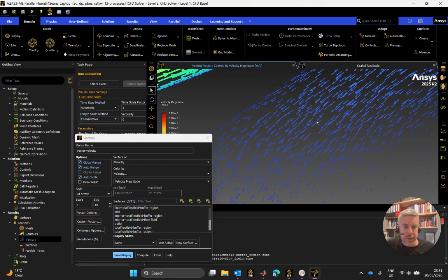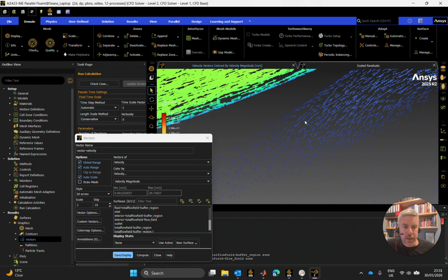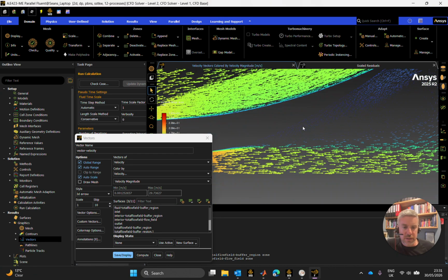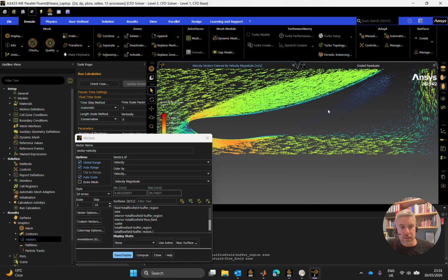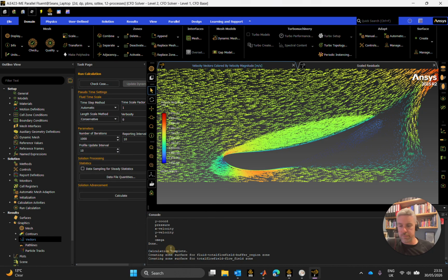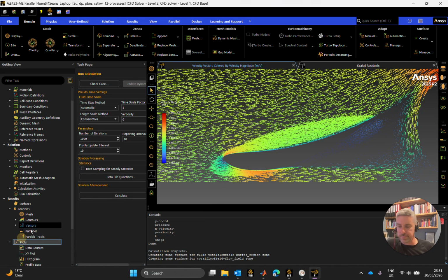This, from an aerodynamic perspective and how we design the front wing, I think this region here is probably the most telling, where we see the separation occurring, which means that we need some way to inject some high energy air back into this region where we've lost energy very fast, to re-energize it, keep the flow attached onto the aero surface, and keep maintaining some downforce. All right, so let's close that up. Plots.